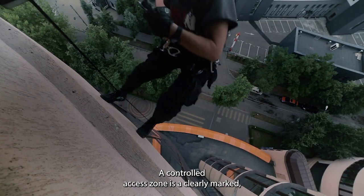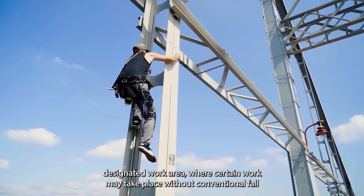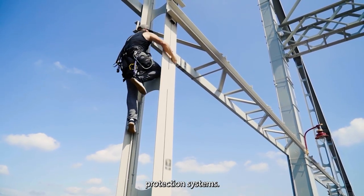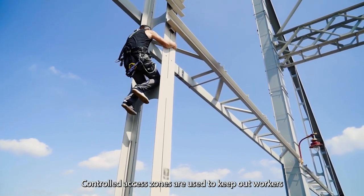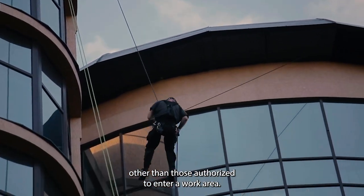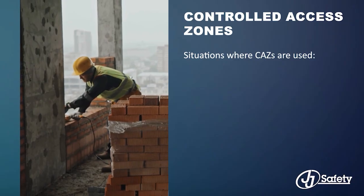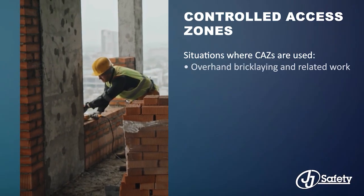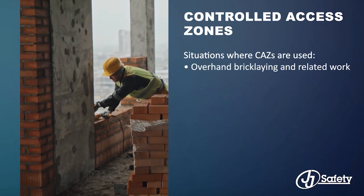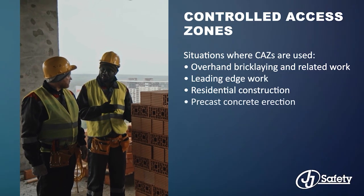A controlled access zone is a clearly marked, designated work area where certain work may take place without conventional fall protection systems. Controlled access zones are used to keep out workers other than those authorized to enter a work area. Situations where controlled access zones are used: in overhand bricklaying and related work, leading edge work, residential construction, and precast